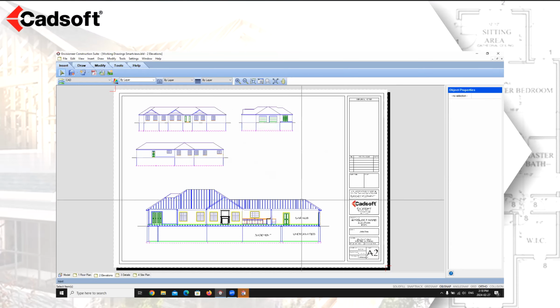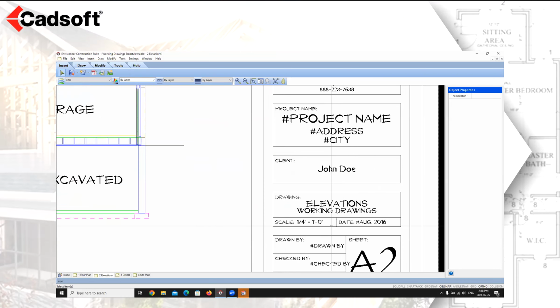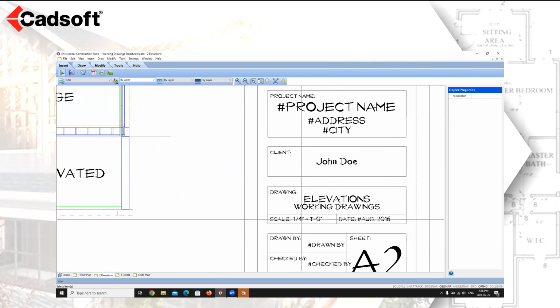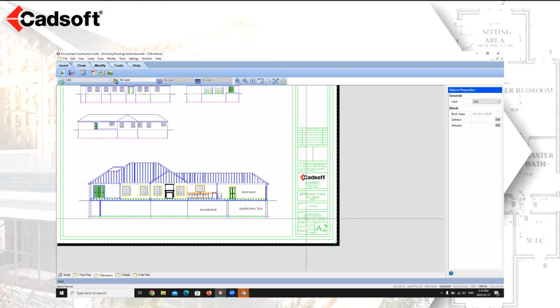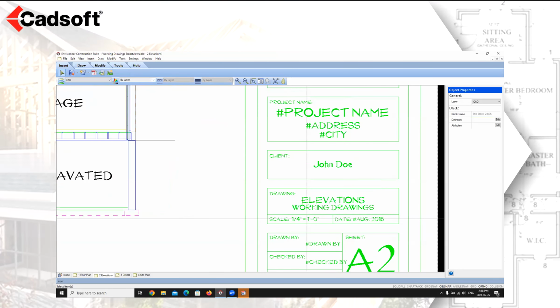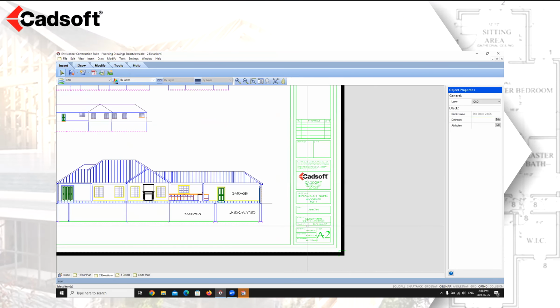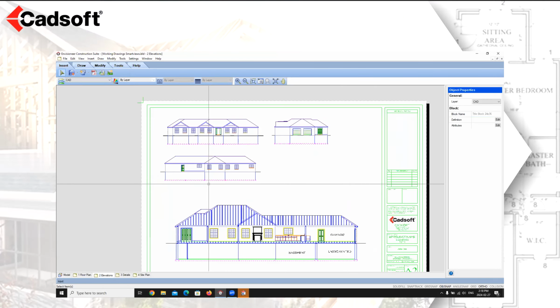And what I would typically do in a scenario like this, where I have differing scales, my title block will say what the scale is of this sheet. I could actually go in and just change it so that it says whatever the majority of it is, or I can have it say refer to sheet, so just RTS, and then underneath each view, I will actually add in the scale.